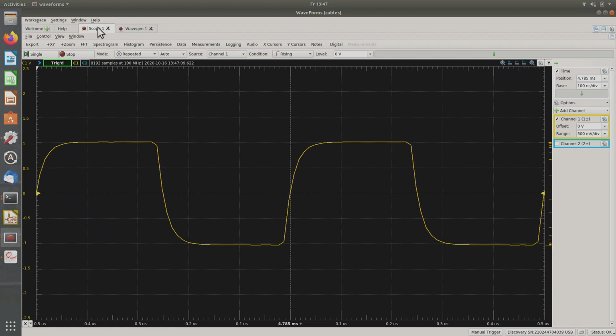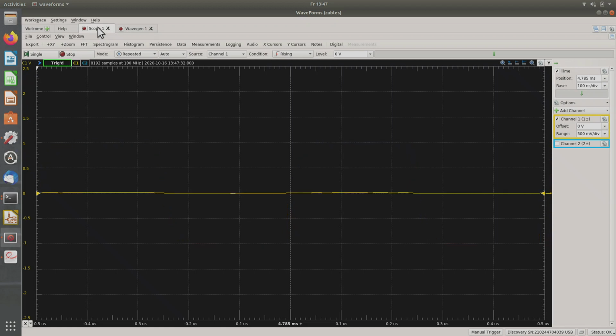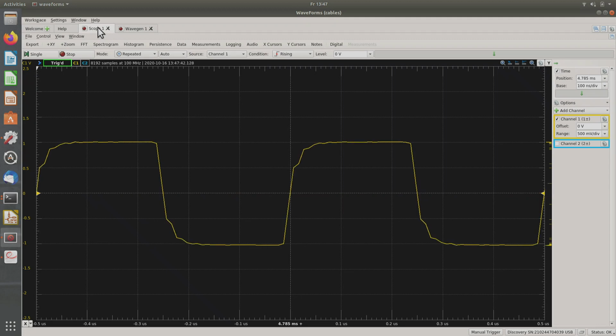The demonstration now is I have a little device here that is a signal generator. It generates this square wave. It has a bit of a time constant that you see when it rises, but otherwise it's a nice signal, and I just directly loop it back via a few centimeters of cable into a receiver that then displays the signal. Now that's for a short cable. The next step is I take a little longer cable. So I go from 2 centimeters or so to 10 centimeters.